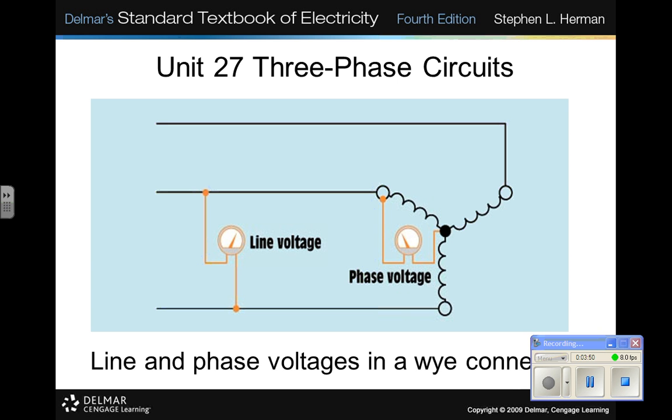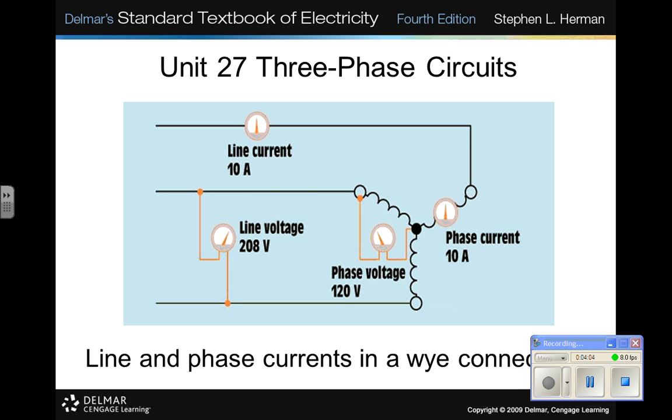And here we see a picture of a three-phase circuit. If we have, let's say, 277 volts across a phase, multiply that times square root of 3, and we'll have approximately 480. And then our currents would be the same, whether it's across a phase or across the line. I want to point out why this is. I said that this is similar to a series circuit, right?